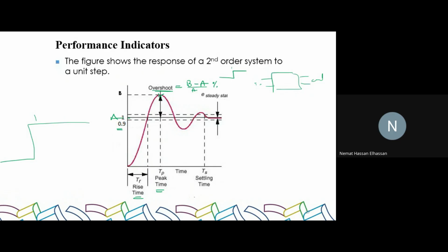So it's very important to understand or evaluate what is the value of the overshoot, or what is the percentage of overshoot? Because if you apply 1 volt and you have 20% overshoot, that means if you apply 4 volts, the 20% of a 4 volt is different than 20% of a 1 volt, right? So you need to know what is the maximum limits of your input. And that's why when you see electronic devices, there is a lot of operating conditions that the input should not exceed this much, and this is based on that evaluation.